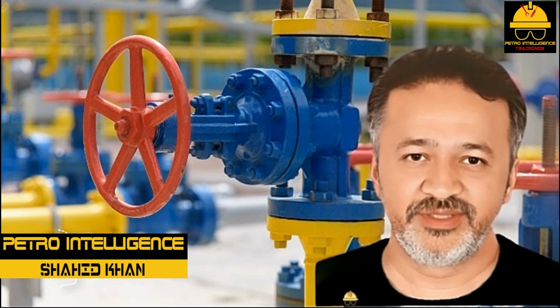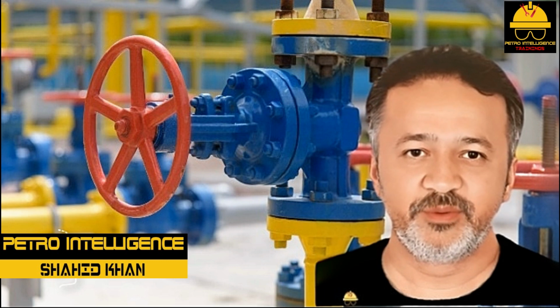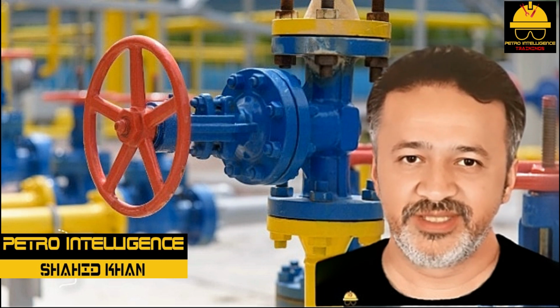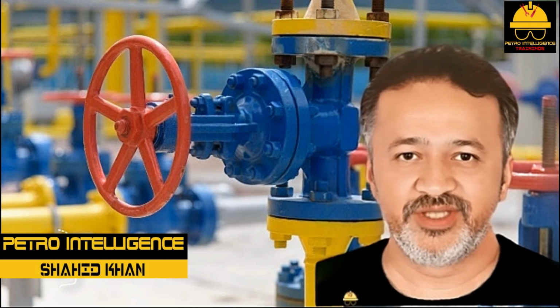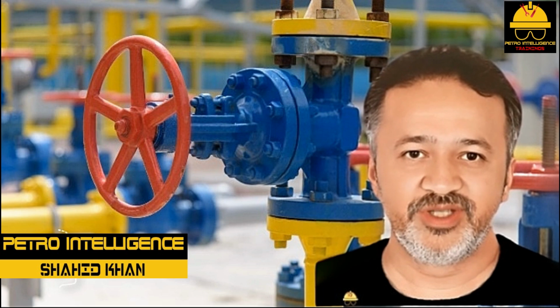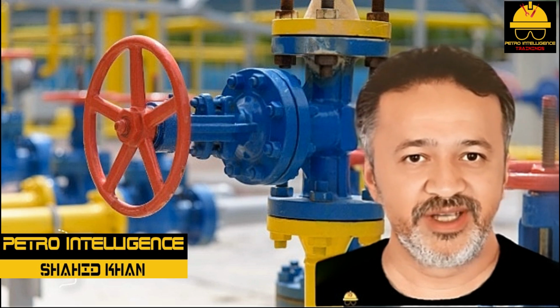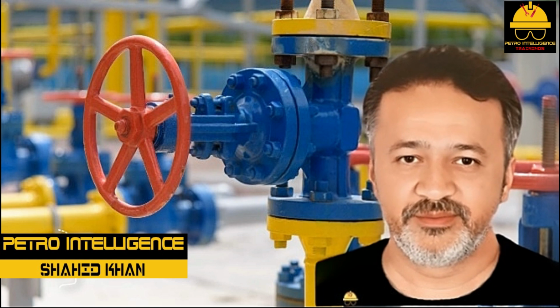The three major differences between a relief valve and a safety valve are liquid versus gas service, the pressure response time, and the larger exhaust port of the safety valve. Relief valves are designed to lift slowly, whereas safety valves tend to pop off. Actuators are devices in a control loop that automatically adjust the position of the valve stem on a control valve.